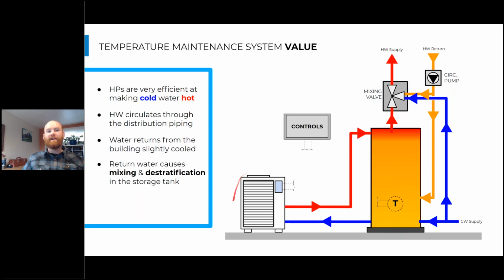So that when this heat pump is turned on now by this thermostat in the tank, it's going to pull in water that's already somewhat heated. And this is a challenging operational point for a lot of heat pump equipment. Because this water is already heated, it's trying to put heat into that water, but it's already heated. So it's challenged to operate at that point.